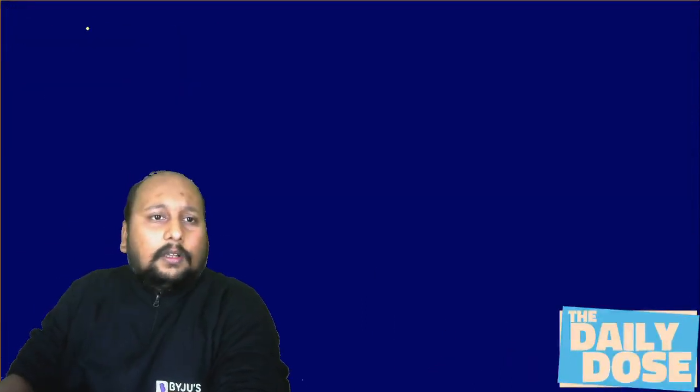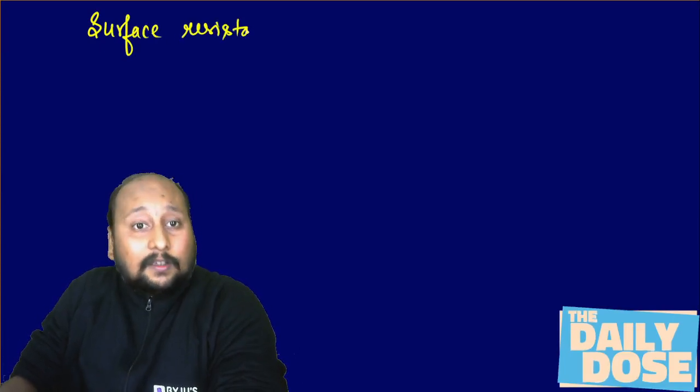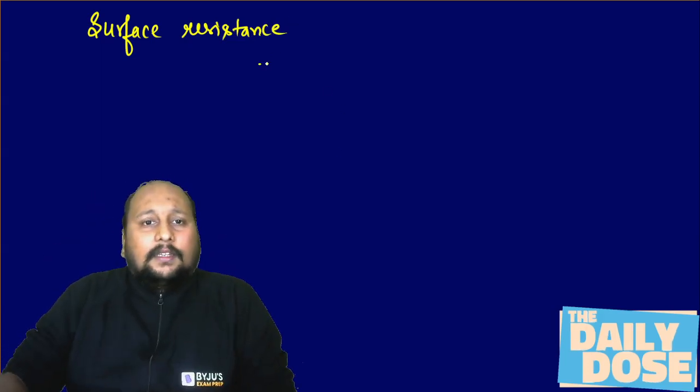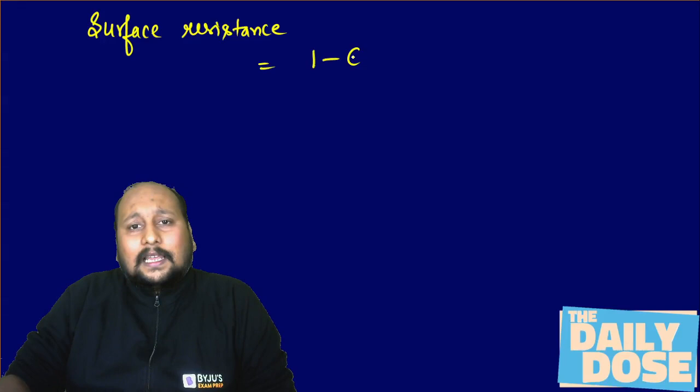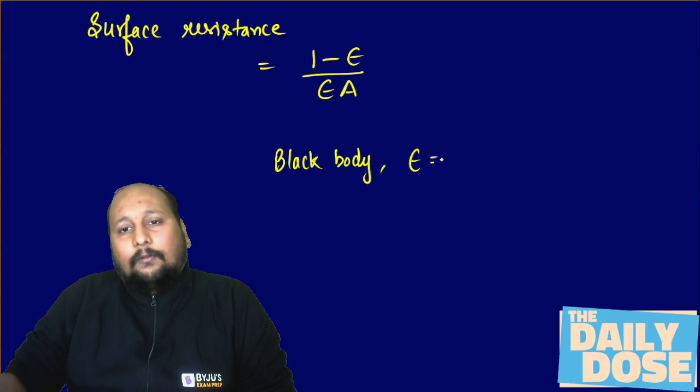If I talk about the surface resistance, now surface resistance basically depends upon the emissivity or the type of surface we have. Okay, because surface resistance is nothing but (1 minus emissivity) upon (emissivity into A). If I talk about a black body, its emissivity is equal to 1. That means its surface resistance will be tending to 0, right?